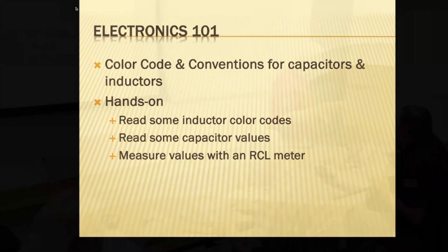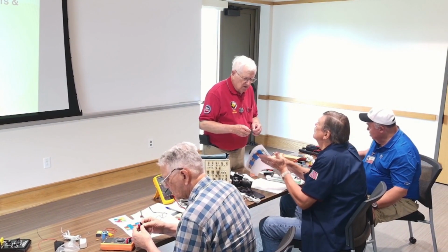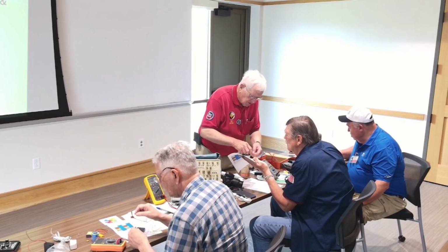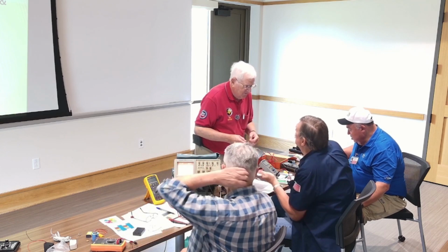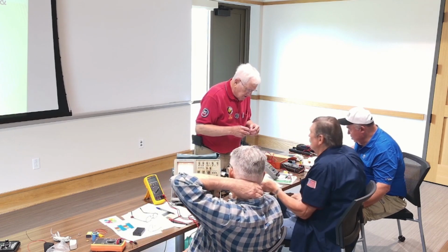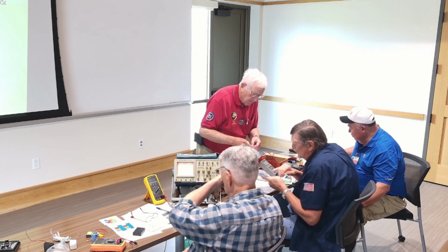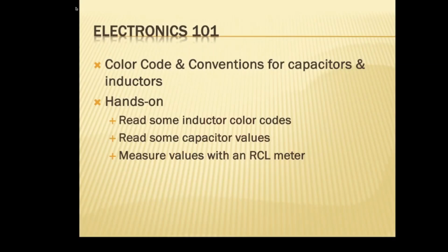That's one of them. That's the military one. This category here. Yep. But the problem is it's got a silver on each end. So does it go that way or does it go that way? Now, in this case, the black, what's the value of black? Black says 0. So we're not going to start off with 0. Okay, so we turn it the other way around.